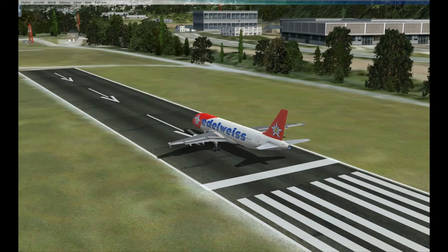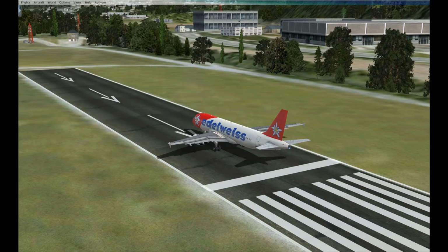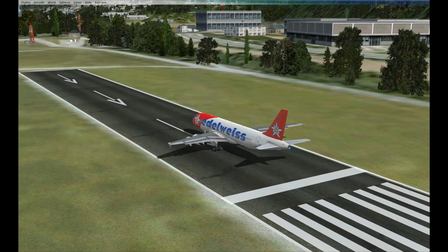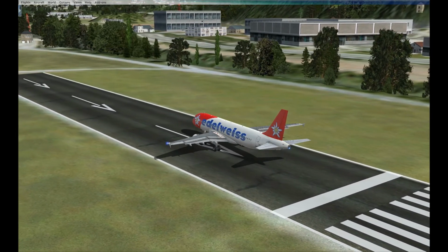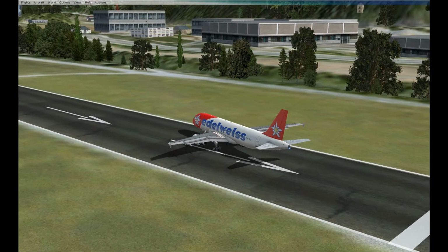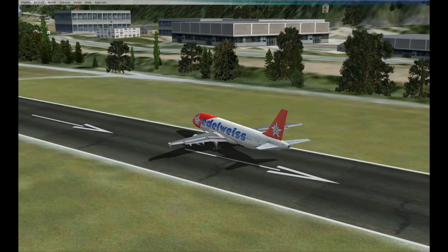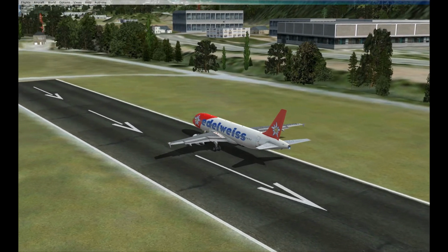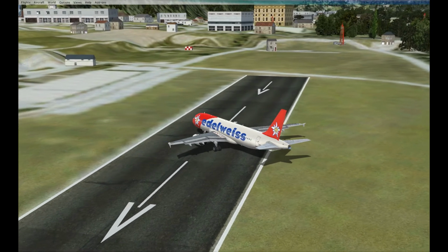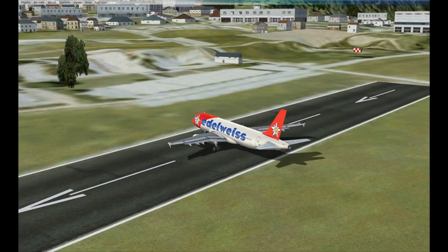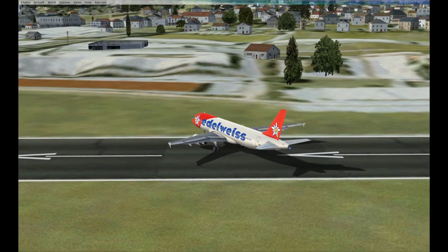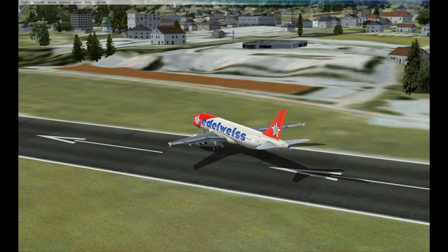Now, although we are safely down on the runway, we have one other minor obstacle. There is no turning circle on this particular airport. So we need to put the nose wheel on the extremity of the edge of the runway, and then a maximum left turn, maximum rudder, possible differential braking to bring the aircraft around within the width of the runway. It can just about be done.